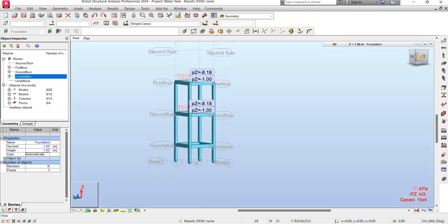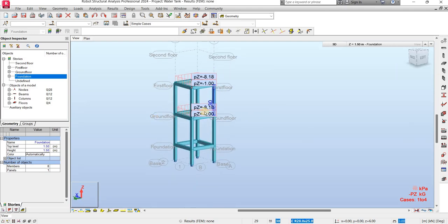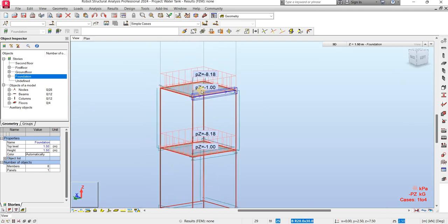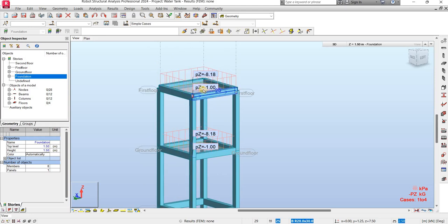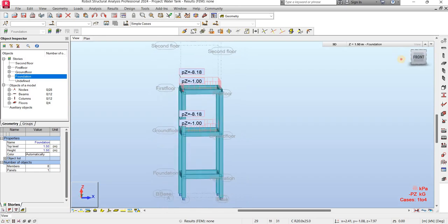And the reason why I wanted to apply the load on the reinforced concrete floor before sending up is because whenever you're sending anything up, it goes with whatsoever load you have applied. So I didn't want to apply load 2 times. That's why I decided to apply all the load on the reinforced concrete floor before sending it up to meet with this other load. So that's it.